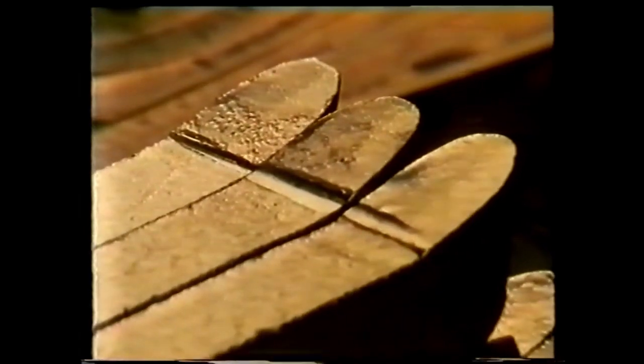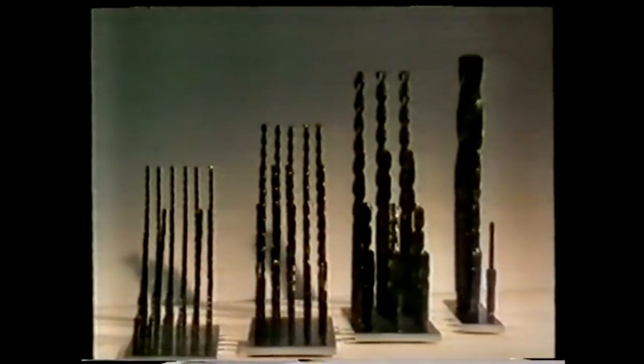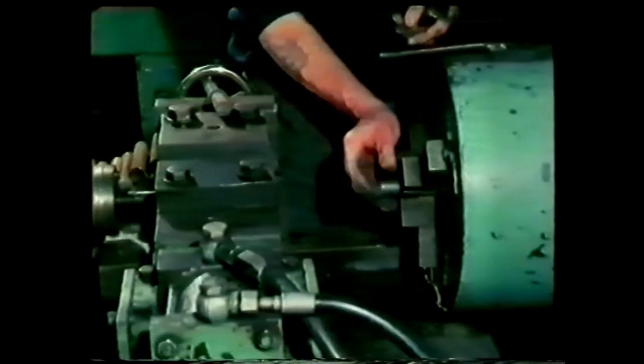Once cleaned, there's one last grinding which imparts a good cutting edge. The cutting edge can be reground again and again until the high-speed steel is completely worn away and the toughened shank is reached. At this point, the tool is scrapped. The same principles are used in other cutting tools, such as high-speed twist drills. As in the lathe tool, only the cutting end is made of high-speed steel. In this particular example, the cutting end is friction welded onto the toughened shank.